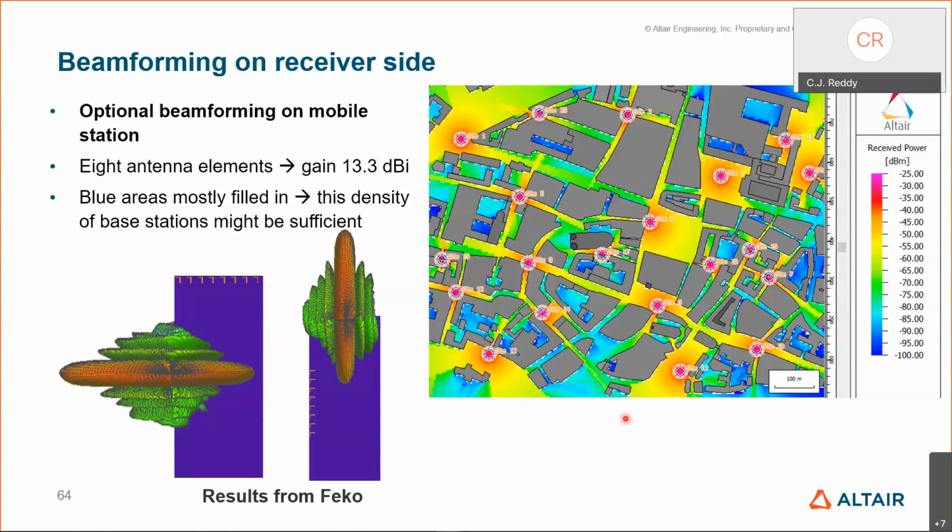With those algorithms, it can form an analytical function for your model. Once it forms the analytical function, it can throw away your actual EM simulations and use that analytical function with those variables to do optimization or anything you want to do. Even if you want to do statistical analysis with tolerances with millions of simulations, because this is an analytical formulation, there's no time, meaning it's all in seconds. In a few seconds you can get your optimization done. In a few seconds you can get your statistical analysis done.